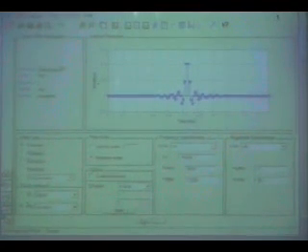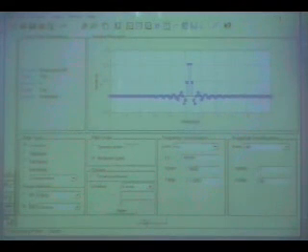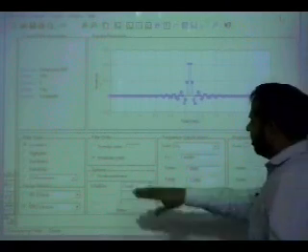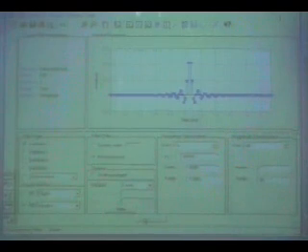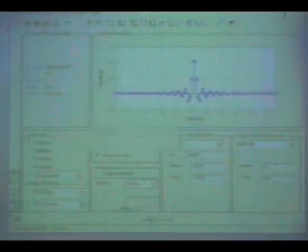So this is the filter which is designed using the Kaiser window. Not the window, the filter designed using the Kaiser window, and you can design any filter. It's your choice, FIR versus IIR. Remember, FIR are always linear phase, zero phase group delay, the constant group delay. So this is the windowing method.